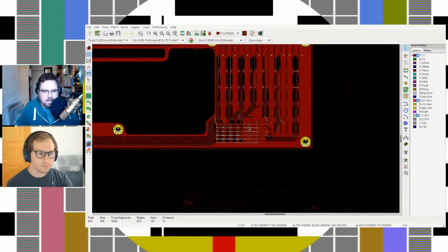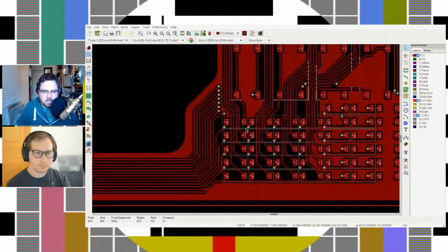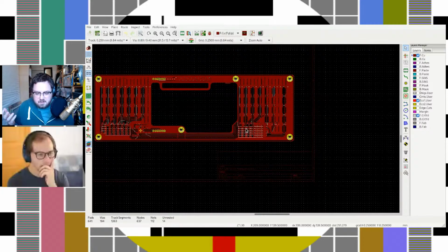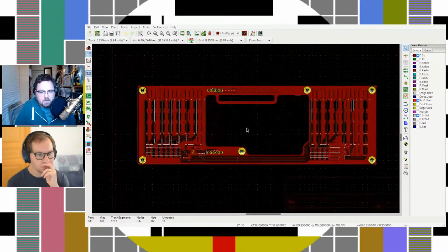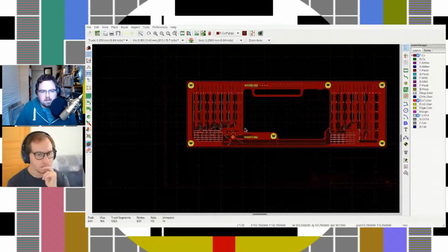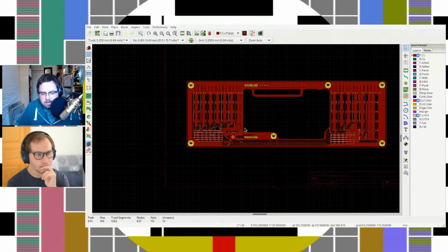So usually what I do is I get all the little tiny touchy surface mount stuff assembled by them. And then if there's something expensive, I'll just hand solder that because it's something special that they don't have. So for this, I only have a little I2C thing. So this isn't a full microcontroller that could do USB. So I'd have to treat this like a module and have the smarter brain part, like the microcontroller that you're actually going to be running code on and is likely to be directly connected to the USB. I would still need something like that.